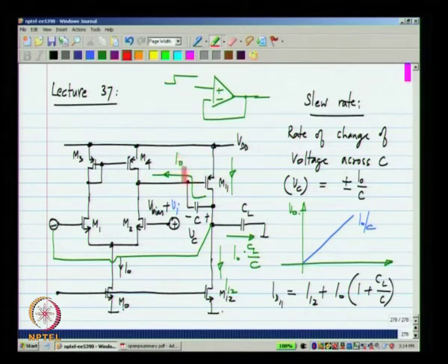Now, is it possible to have that value? Yeah, because in quiescent condition, the voltage here would be such that the current through M1 equals I12. Now, as Vi increases, this voltage reduces slightly, and that increases the current in this. The total current here is limited by how far the voltage can go, but we will assume that it is not limited. So, the current in M11 can increase in the positive direction. While it is I12, it can easily become this value by lowering of the gate voltage.